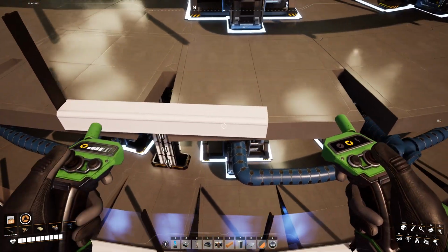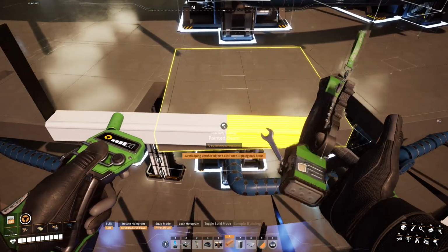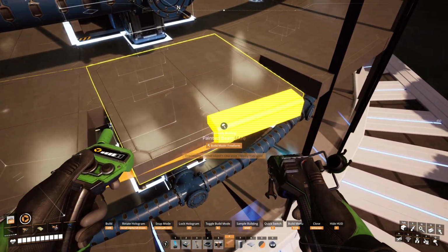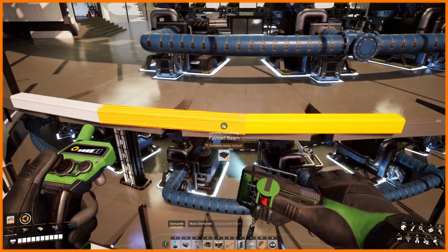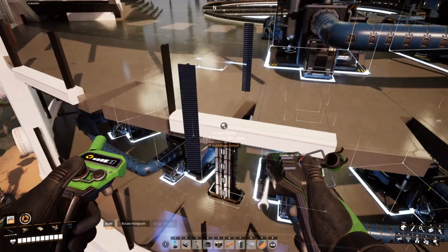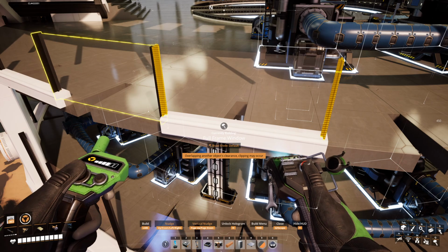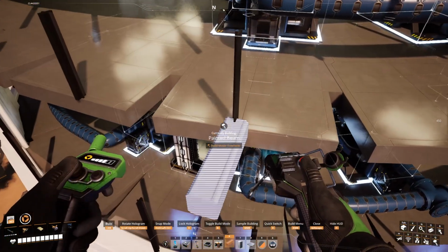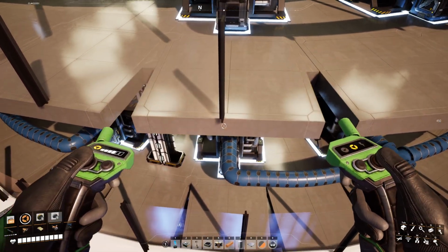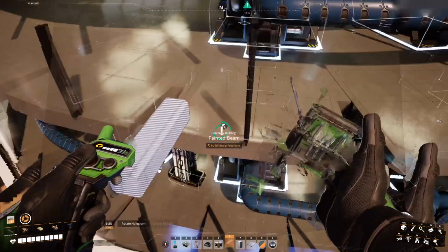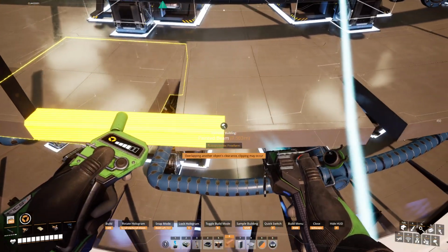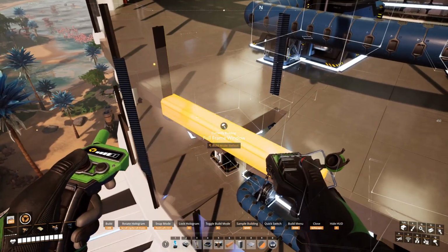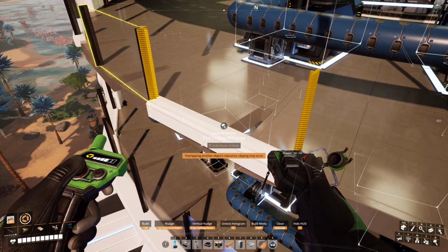So going just past 8 meters, obviously there's going to be a small discrepancy, but every time that you take it, you're going to be putting it in position again. You're kind of resetting that angle every time. So even though there's a slight discrepancy in the length of the buildings, as soon as you put this one down, you are recommitting that 8 meters to this kind of concept. And because you start on that edge again, you can maintain this angle pretty much indefinitely by just repeating this technique every time.